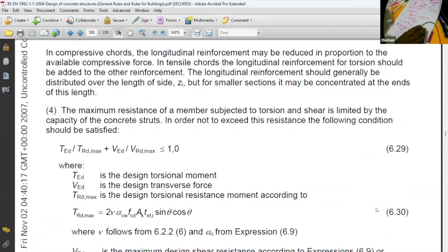And if a rectangular section is not adequate, don't increase the depth, because you are not going to gain much. Always increase the width, because we know square sections are far better than rectangular sections when it comes to shear.